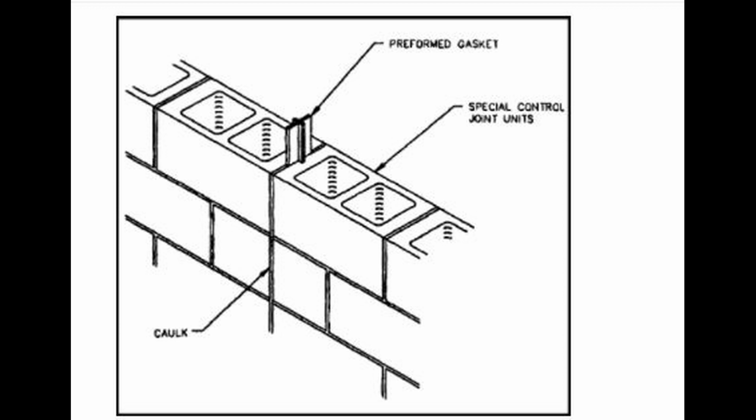Masonry wall construction is going on in a desert area. Therefore, based on the level of humidity, the control joint should be apart by 12 feet. The provided distance, which is 20 feet, is much larger.